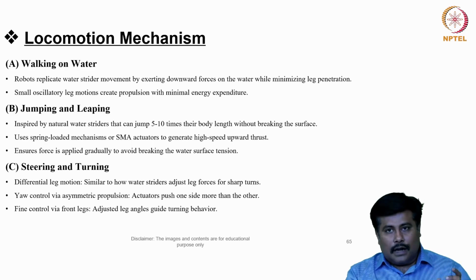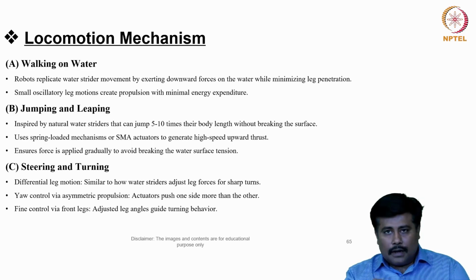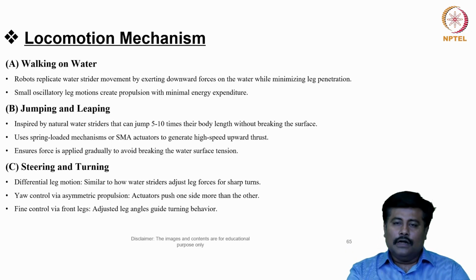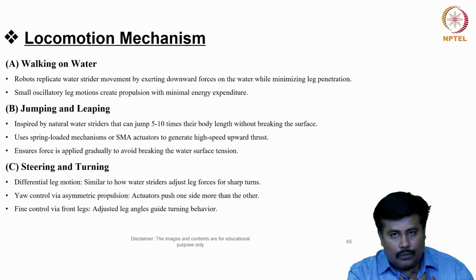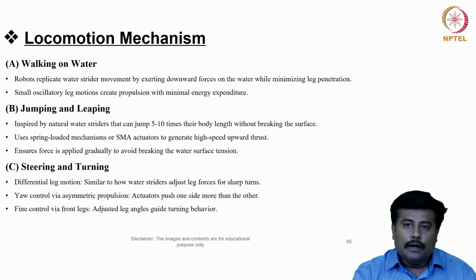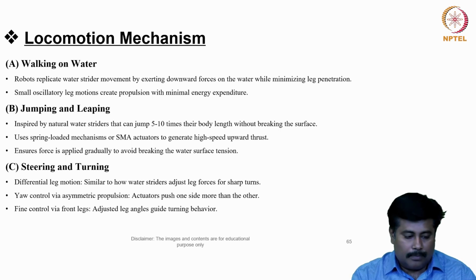It uses a spring-loaded mechanism or an SMA actuator to generate a high-speed upward thrust motion, and it ensures the force is applied gradually to avoid breaking the water surface tension. Now when we look into the steering and turning locomotion, it has a differential leg motion, similar to how a water strider adjusts its leg force to make sharp turns.